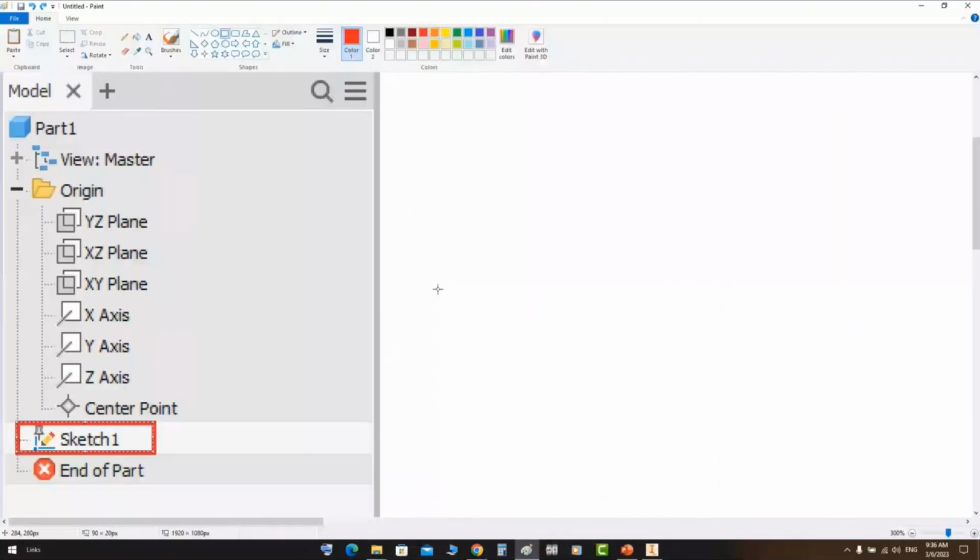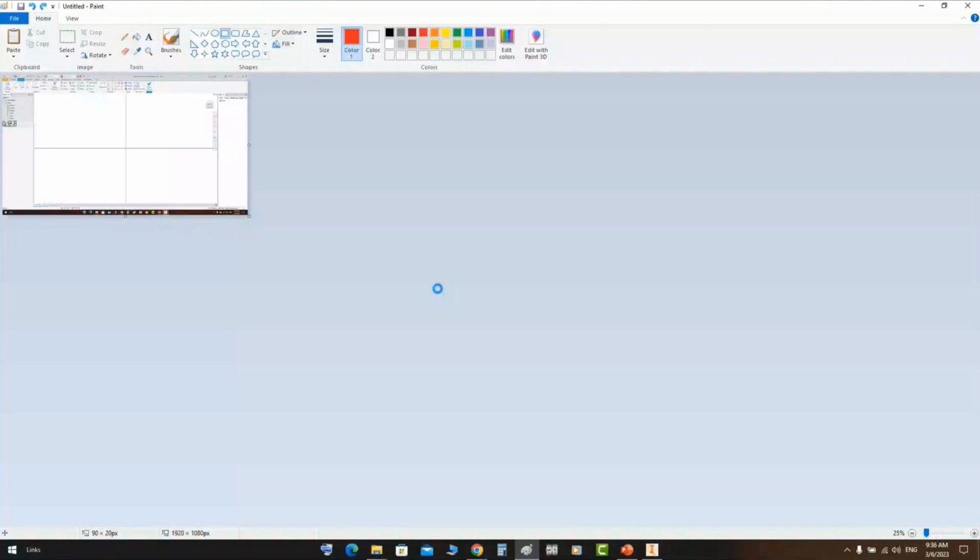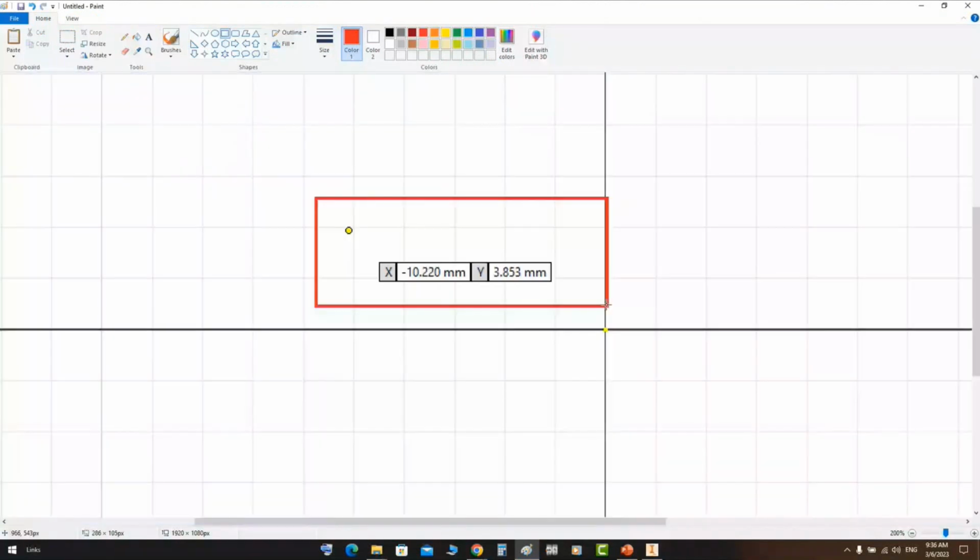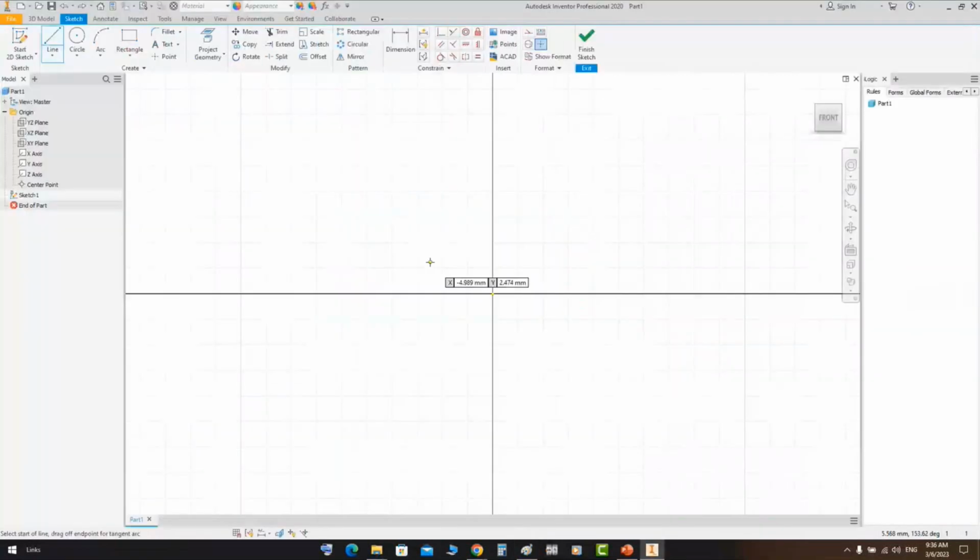If you take a look here, you can figure that this point, the located point that you stand on right now, has a location in X and Y. So you can define the first point in X and Y. From here, if we select the line, you can define the locations of X and Y, and you can move between them by clicking Tab.